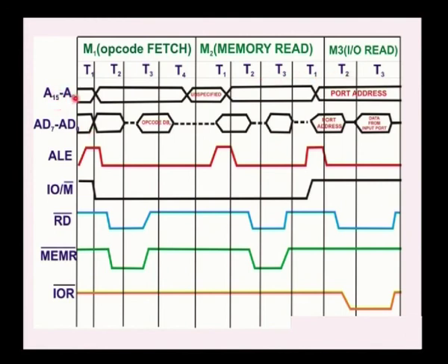For the address lines, first we have to draw the higher order address lines A15 to A8. We connect this till T3; the T4 state is unspecified, which represents that the address is already read, and the 3 T states are used to read the addresses. Then for the multiplexed address and data lines, in the T2 state we have drawn only the address, and from part of T2 to T3 we have drawn the data lines. This is repeated for all machine cycles.